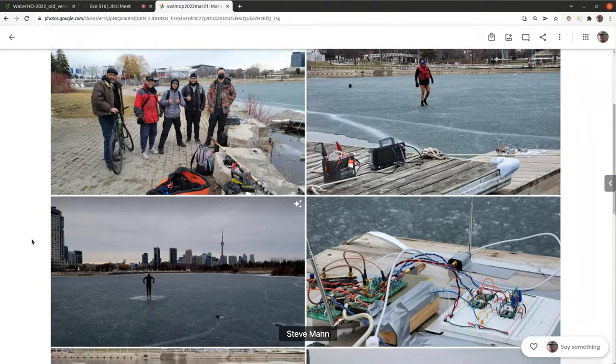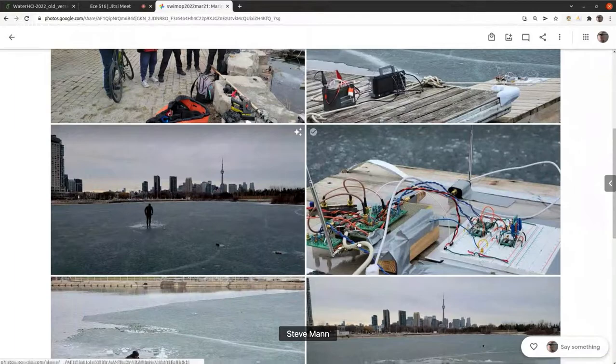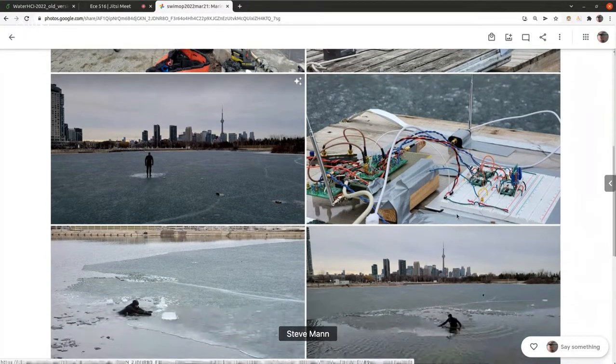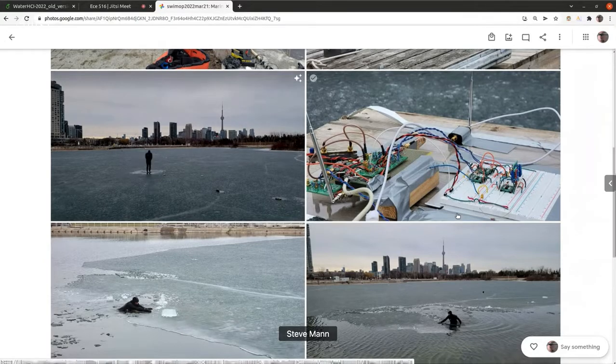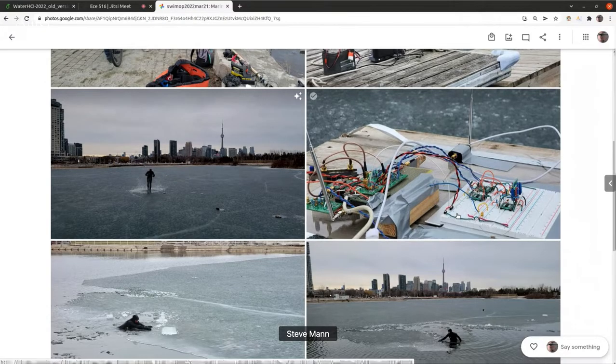It hasn't formed solid. And so this radar set here has some low noise amplifiers, a Gilbert cell, which does multiplication. It's basically a lock-in amplifier, which is designed to operate at the frequencies that we're transmitting at. This radar is 2.5 gigahertz. The other one that I showed you is 24 gigahertz. Some marine radars, a lot of them are around 10 gigahertz or so, like 10.525 gigahertz, is a very common marine radar or amateur ham radio frequency that people use.